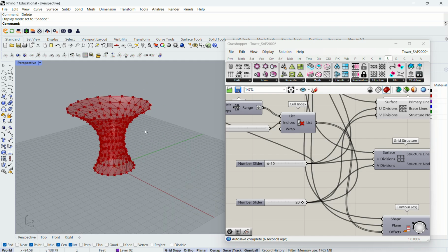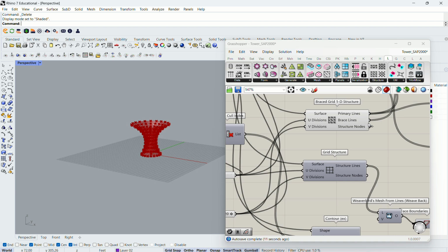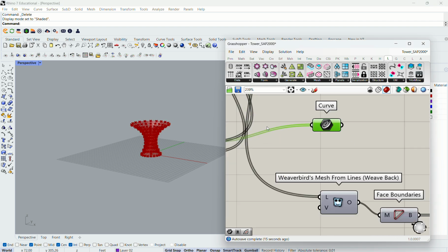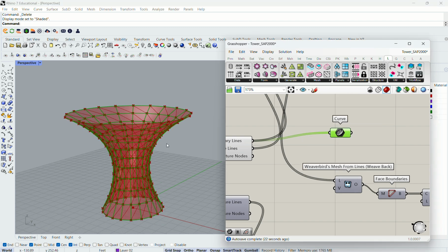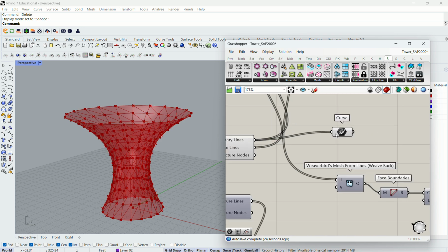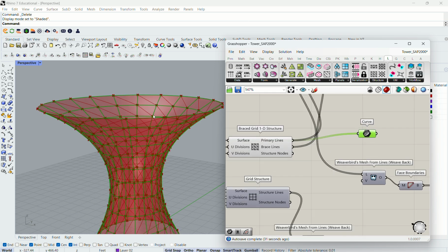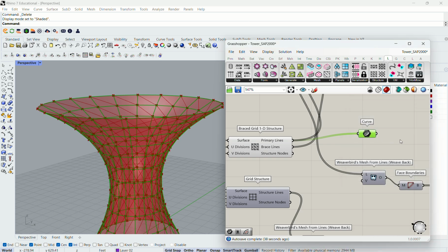All right, so I already have all the subdivision using this plugin, and I also grab some curves. I have to think about how to export it separately so that I can easily handle that group of members. First, the curve: you see the vertical primary lines, representing vertical and horizontal members. I'm going to bake them to layer 1.